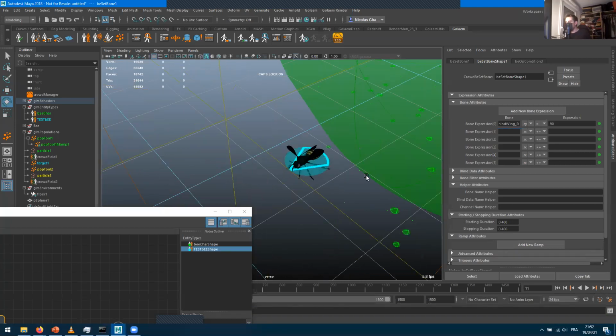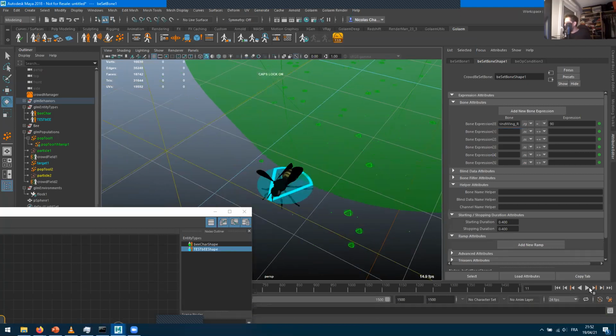Yeah, great. So here we're making a slow transition between T-pose and the 90 degrees orientation on that character, and we can probably do this on the left wing if we've done stuff properly. They're probably named with the uppercase, like the opposite, hind wing underscore L, probably on the y-axis too, and probably 90 degrees too, that we want to override the value with. And it's minus 90 degrees, obviously.